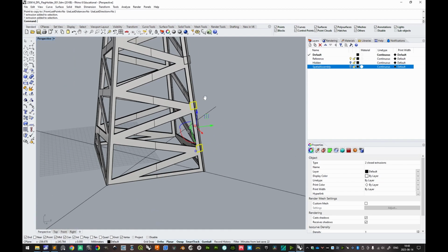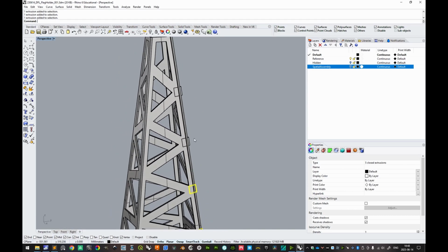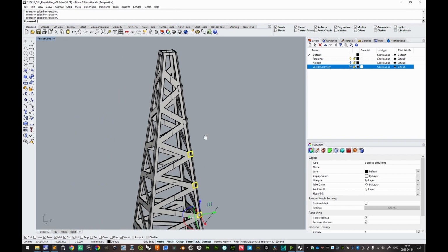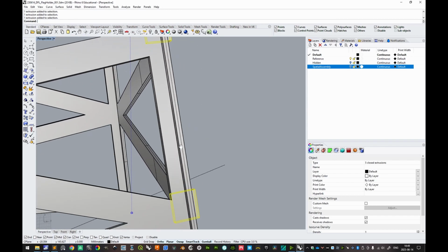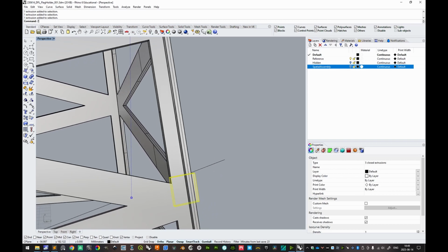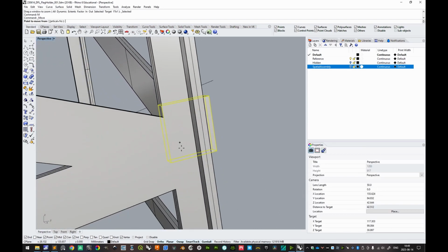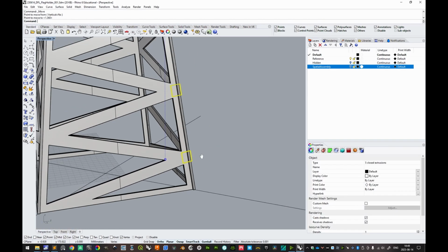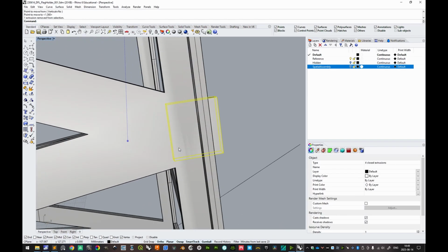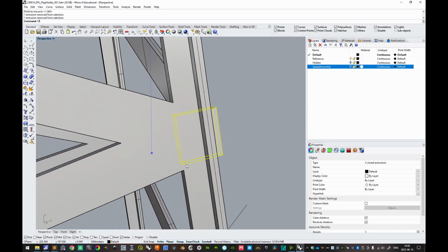If we select every one of them, except those two that are actually quite good, and then we do like this. If you lose the orbiting point like I've done, it's easiest to just type Z/S to zoom to selected, and then you are re-orbital. Very good, and then move, and the first reference point, second reference point along the axis, press Tab on the keyboard, and then now this is good. It's here, and then this is good. It's definitely okay.